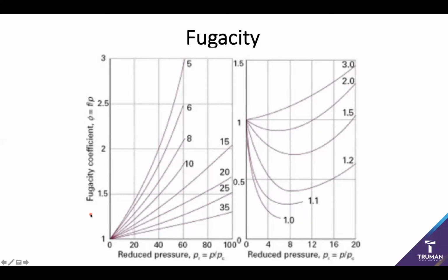The system will always act with a higher free energy value than would be predicted from ideal behavior. However, this expression is essentially emphasized as we start reaching critical temperatures that are much lower. So again, a cold system at high pressure is going to act with a much higher fugacity coefficient and thus a much higher free energy than we would normally expect from ideal systems. In fact, as much as 2 or 3 times as high.